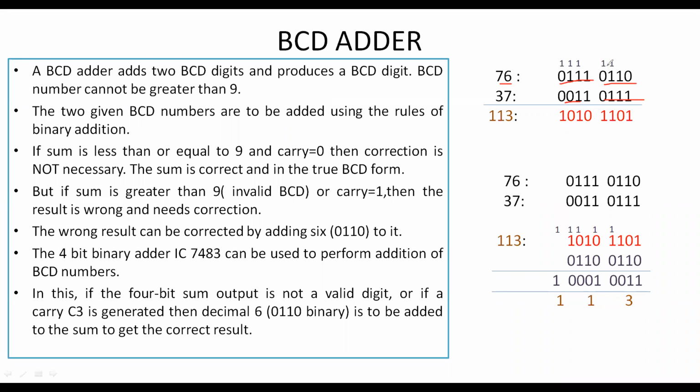And observe, by the addition of these two, we are not getting any carry. By performing the addition of the first 4 bits, verify whether any carry is generated from the first 4 bits. We need to check whether a carry comes from the 4th bit to the 5th bit. There is no carry generated. This is the first point we need to remember.